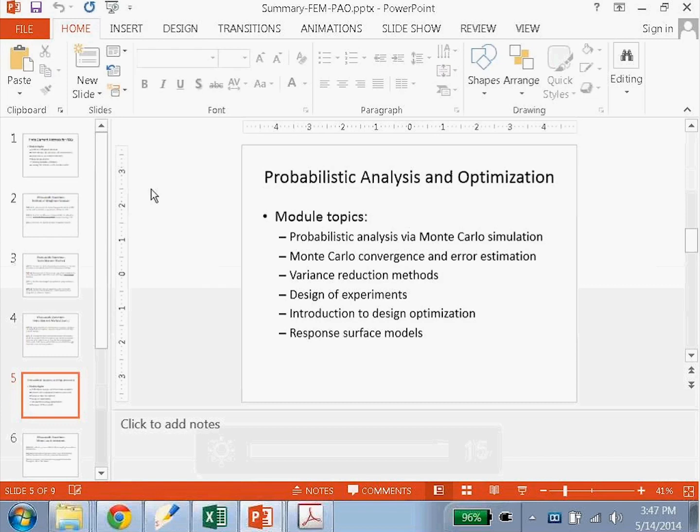The idea is that we would define factors, which are inputs, and we would define discrete levels at which we might want to test those factors. We're going to run some combination of factors and levels through the model and collect outputs, which are sometimes called observations in DOE language. The different DOE methods are different ways to choose combinations of factors and levels.